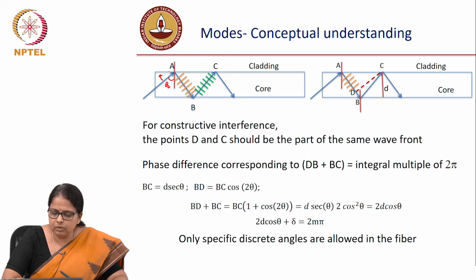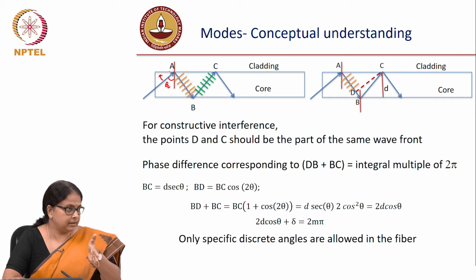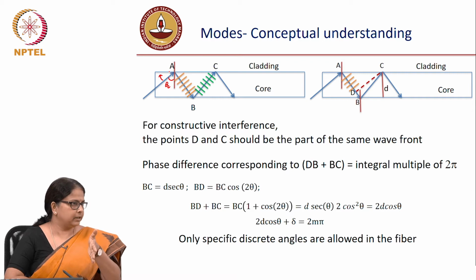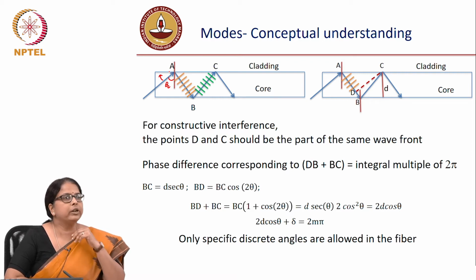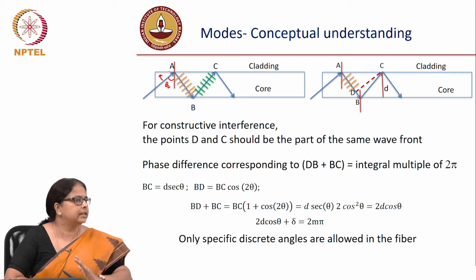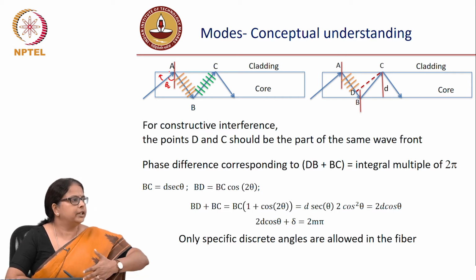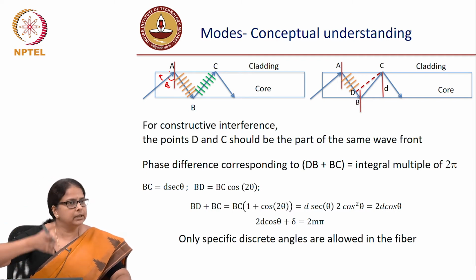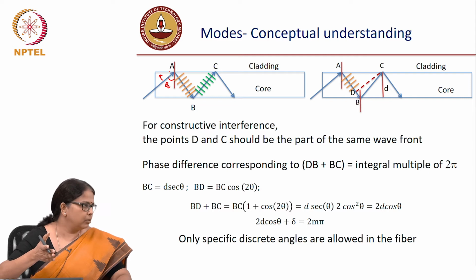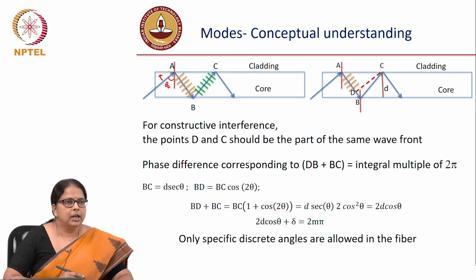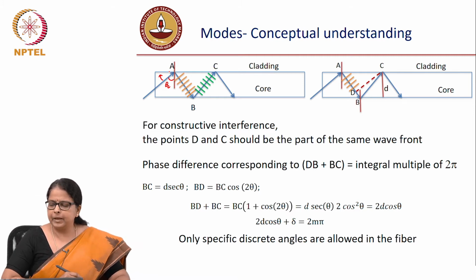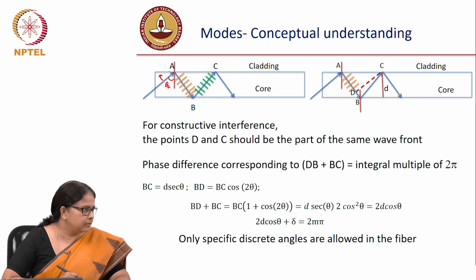Okay. But now these transverse modes, we still do not know what is the spatial pattern, and I said that what distinguishes the transverse mode is the spatial xy pattern of that mode. This analysis will not give you that, it is just telling you that only discrete modes are possible. It can also potentially tell you at what angles each of these modes is supported, but it is not telling you what the transverse profile of the modes looks like. So, the next couple of lectures, I hope we will not need a couple of lectures, is to derive the transverse modes of an optical fiber.